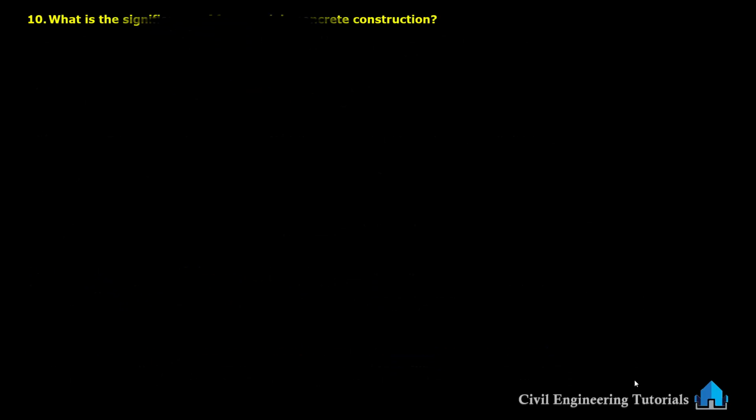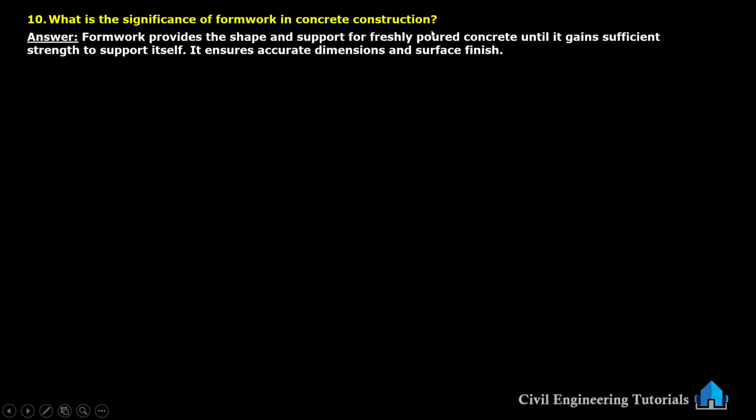Now 10th question. What is the significance of formwork in concrete construction? Formwork provides the shape and support for freshly poured concrete until it gains sufficient strength to support itself. It ensures accurate dimensions and surface finish.